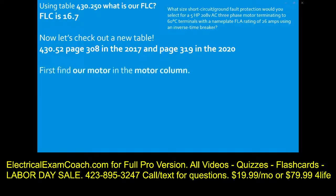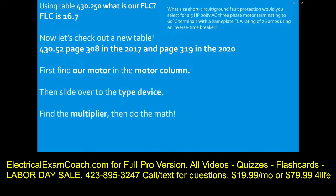First, we find our motor in the motor column. We go down to polyphase. I want to let you know that that just means three-phase. Now we come over and tee off with our type of device. In this question, it was an inverse time breaker. Now what we do is we take that multiplier and do the math. We take our FLC, which is 16.7, we multiply it by 2.50. That is going to give us a new amperage to size our breaker by of 41.75.